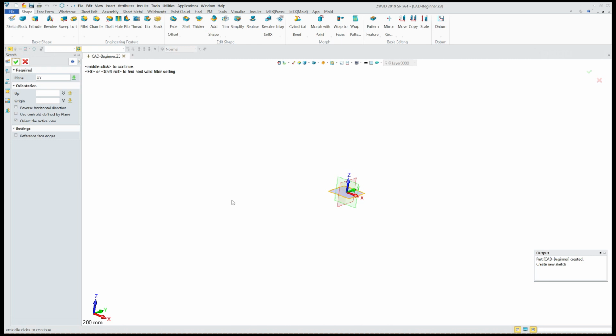And then we have the option to choose the point of origin of our sketch in relationship to the point of origin of our part. You see that depending on where we hold the point on our screen, the point gets assigned a specific value on each axis. For example, if we only move the point in the X direction, the value only changes in the X axis. And if we go past the point of intersection in the other direction, the value changes to a negative value. And the same thing goes for the Z axis. Here we have a positive value, and past the point of intersection we have a negative value. And the same goes for the Y axis. So this is very good to know if you want to place a sketch on a specific location.